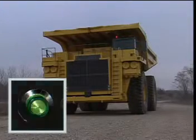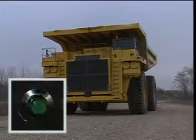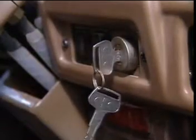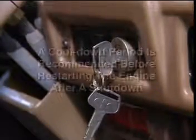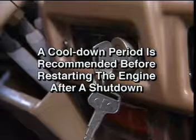After any engine shutdown, the reason for the shutdown should be determined and corrected before continuing operation. The ignition key must be turned off for several seconds before attempting to restart the engine. A cool-down period is recommended prior to restarting the engine after a shutdown.